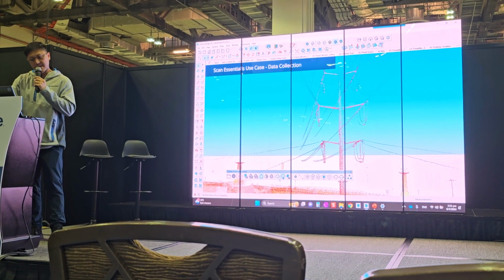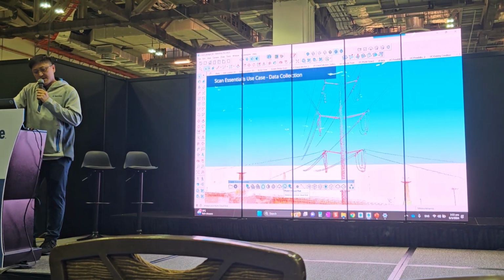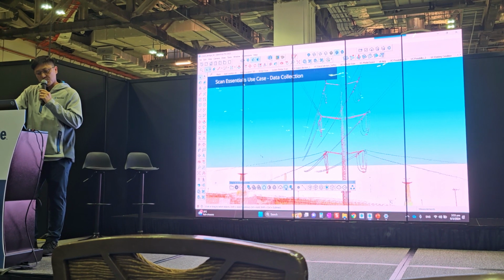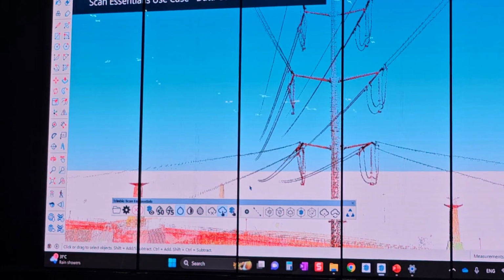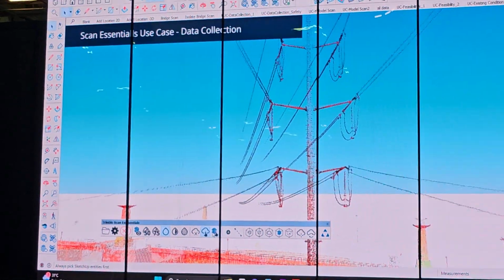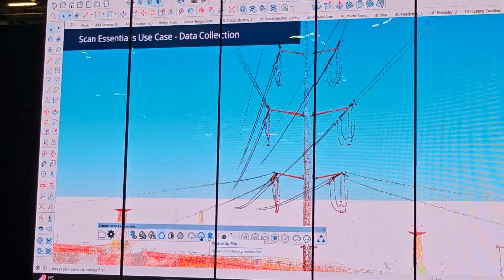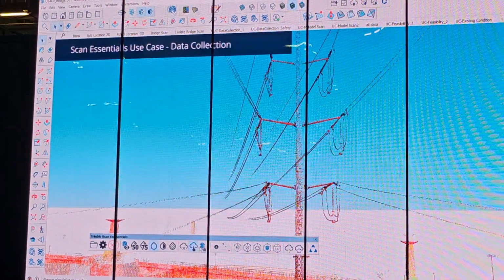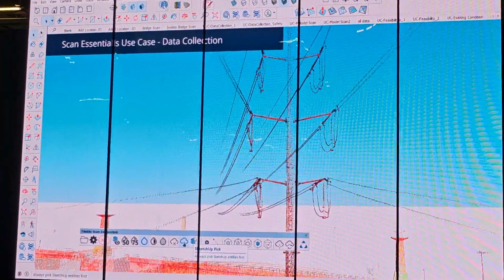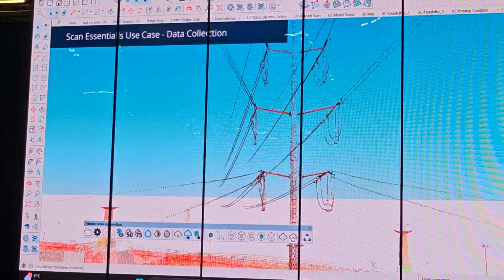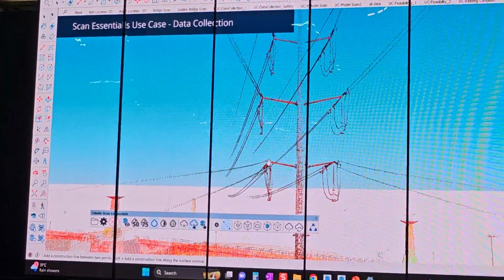We have a toolbar here, and it really is using some of the drawing tools in here to actually model. One of the things I wanted to show you was that I can always straddle between the point cloud pick and the SketchUp pick, and that's really the trick to model in 3D from point cloud. So over here, I'm just going to draw a simple line, just to show you.